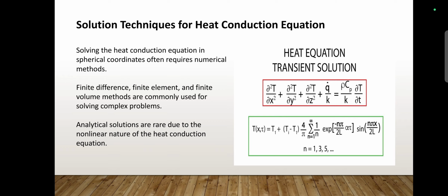Solving the heat conduction equation in spherical coordinates often requires numerical methods. Finite difference, finite element, and finite volume methods are commonly used for solving complex problems. Analytical solutions are rare due to the nonlinear nature of the heat conduction equations.